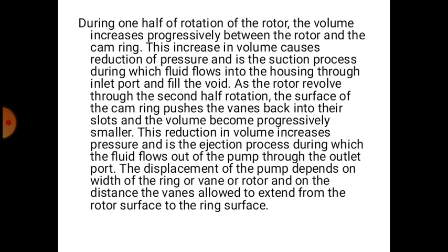During one half of rotation of the rotor, the volume increases progressively between the rotor and the cam ring. This increase in volume causes a reduction of pressure in the suction, and this is the suction process, during which fluid flows into the housing through the inlet port and fills the void.